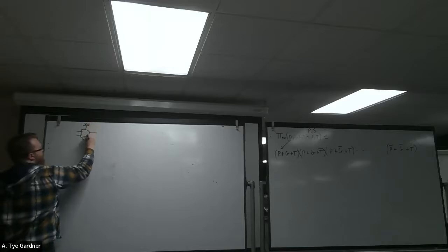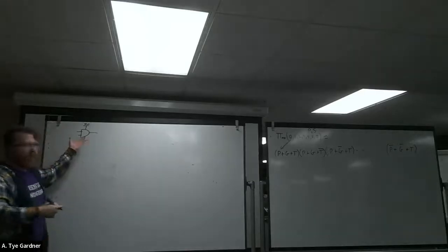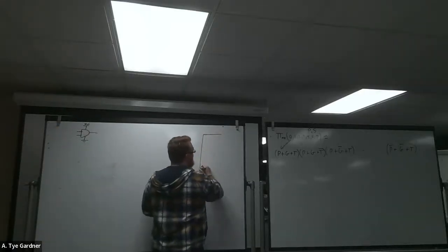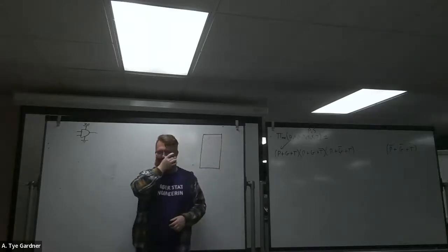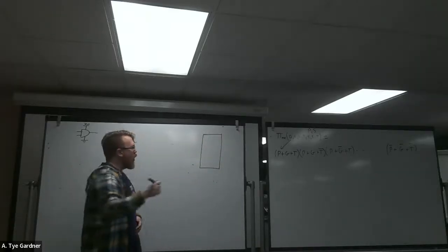And even this could be more specific, right? Because technically this needs a power and ground to tell it what voltages are 0 and what voltages are 1. Well, besides that, what happens when I want a 4-input AND gate? How do I build a 4-input AND gate? Draw 2 more lines. Yeah, I draw 2 more lines, right? But let's say that I gave you an IC package of only 2-input AND gates, right? Because that's a possibility, because we have these blocks of chips, and I'm going to do this with actual NAND gates to you in the next lab, where